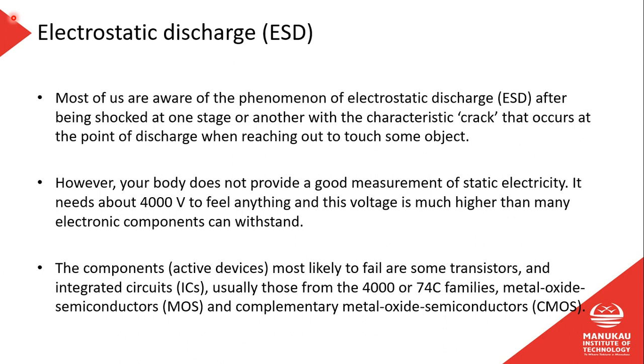Right. So ESD, most of us are aware of the phenomenon of electrostatic discharge after being shocked at one stage or another, with the characteristic crack that occurs at the point of discharge when reaching out to touch some object. However, your body does not provide a good measurement of static electricity. It needs about 4,000 volts to feel anything, and this voltage is much higher than many electronic components can withstand. The components of active devices most likely to fail are some transistors and integrated circuits, usually those from the 4000 or 74C families, metal oxide semiconductors, and complementary metal oxide semiconductors.